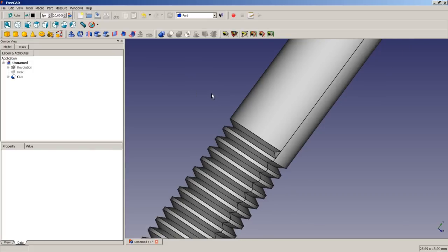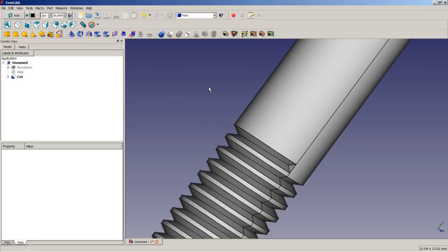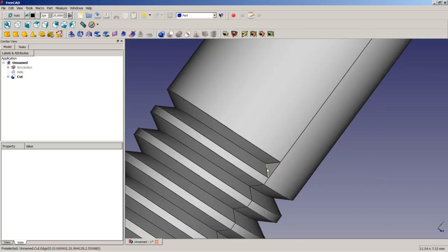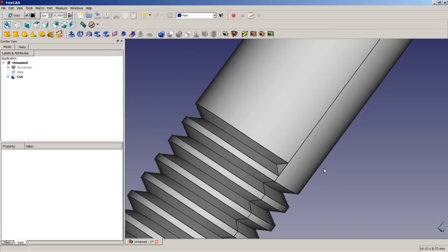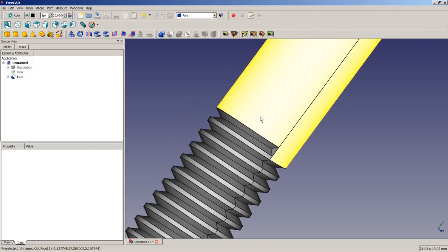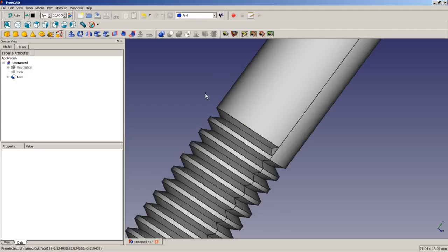If you will try a pocket operation here, FreeCAD will issue an error and will refuse to do the operation. So we do cheat, we do the sketch, and we do not pocket it. We will pad it and then apply a Boolean operation, which will result in a nearly correct shape in the end.